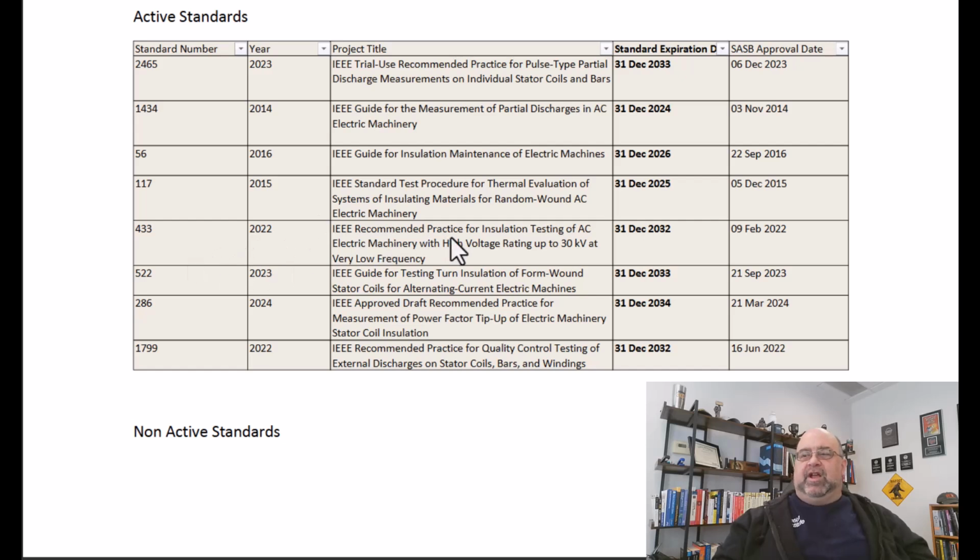433, IEEE recommended practice for installation testing of AC electric machinery and high voltage rating up to 30 kV at very low frequency. This is the famous VLF test, which somebody was trying to explain to me recently did not exist as a standard, and I said, yes, it does, and here it is, 433.